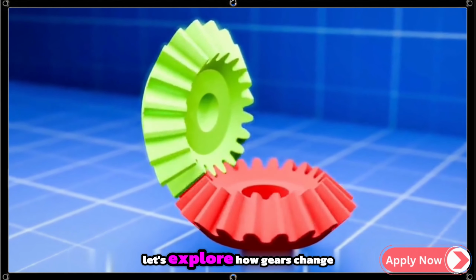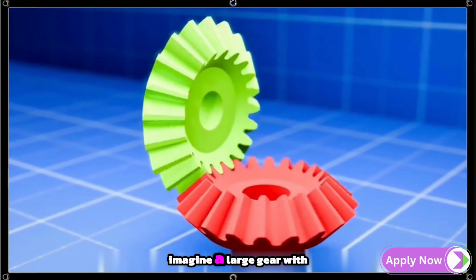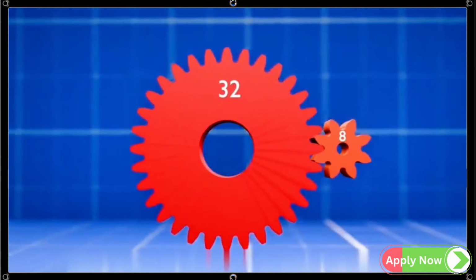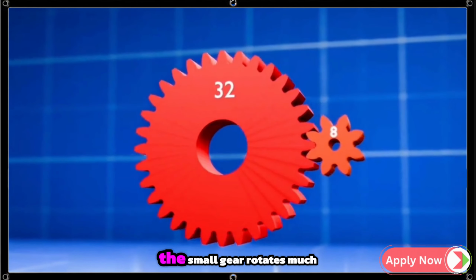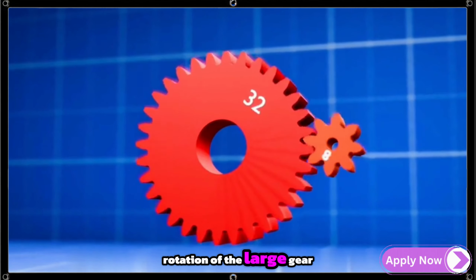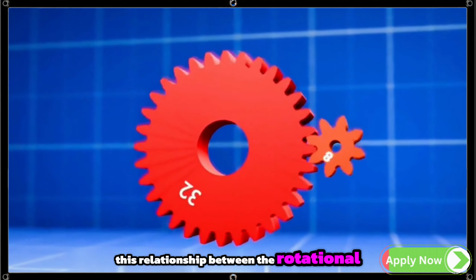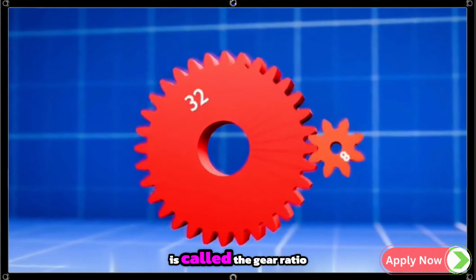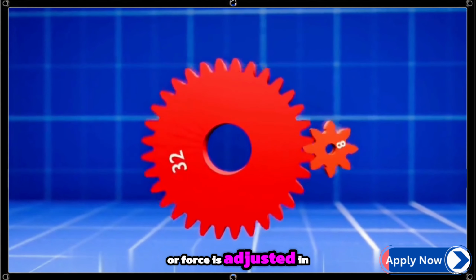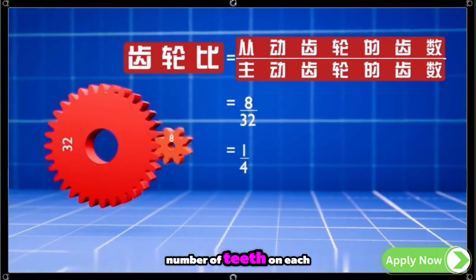Now, let's explore how gears change motion speed and the forces they generate. Imagine a large gear with 32 teeth, meshing with a small gear having only 8 teeth. When you rotate the large gear, the small gear rotates much faster. In fact, for every full rotation of the large gear, the pinion will rotate 4 times. This relationship between the rotational speeds of the two gears is called the gear ratio. The gear ratio determines how speed or force is adjusted in the gear system. To calculate the gear ratio, you simply look at the number of teeth on each gear.